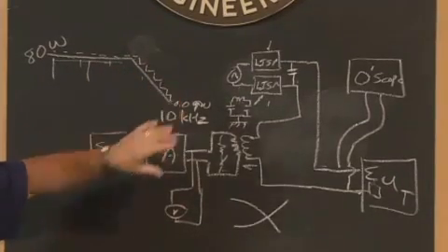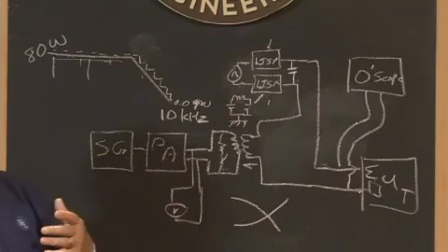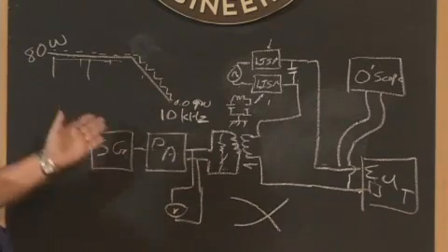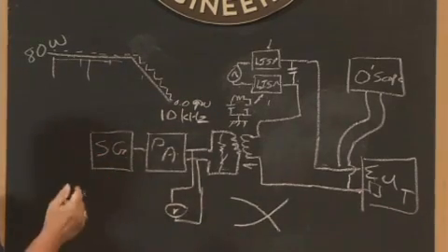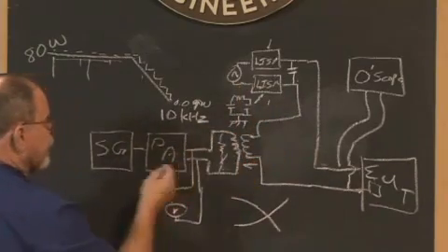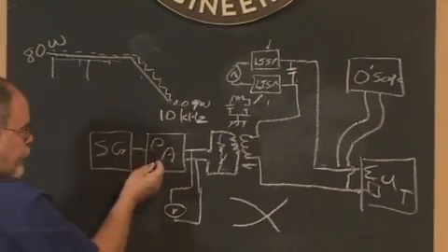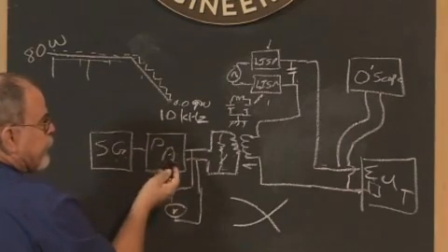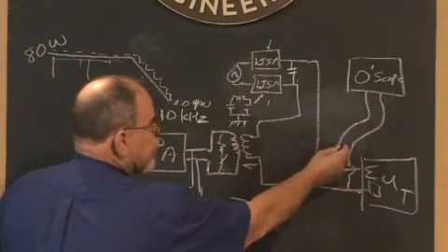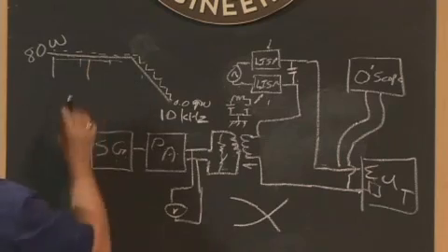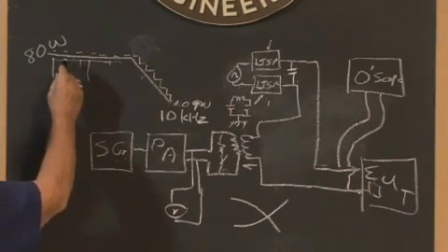So now that we have this process ready to go, all we're trying to do is apply an interfering voltage. Assuming we get everything to start up, we apply the interfering voltage. We turn the signal generator on with the power amp, elevate the voltage until we measure the test limit. Now we're talking test limit. This is a forward power limit.